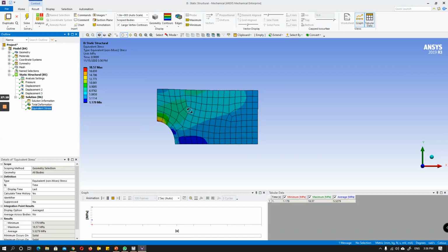Like I said, you can do it with the whole model. Some of it might work. For me it did not work, so this is much easier to do. It takes less computation time. Since it's symmetric, you just need to study the characteristic of one quarter here, and you can map this to all the other 3 quarters as well. You can probe all the values, the minimum, maximum, all this you can do. With that, we will finish this experiment and we will do another one in the next video. So thank you.